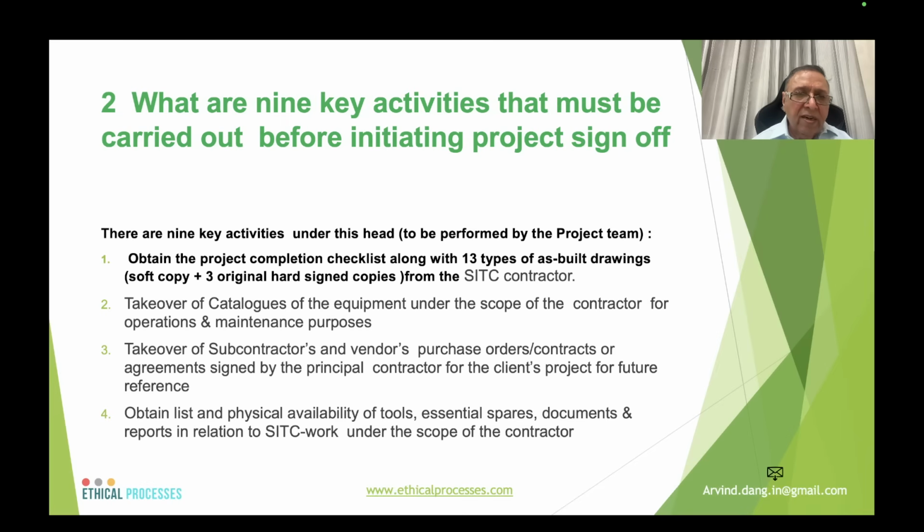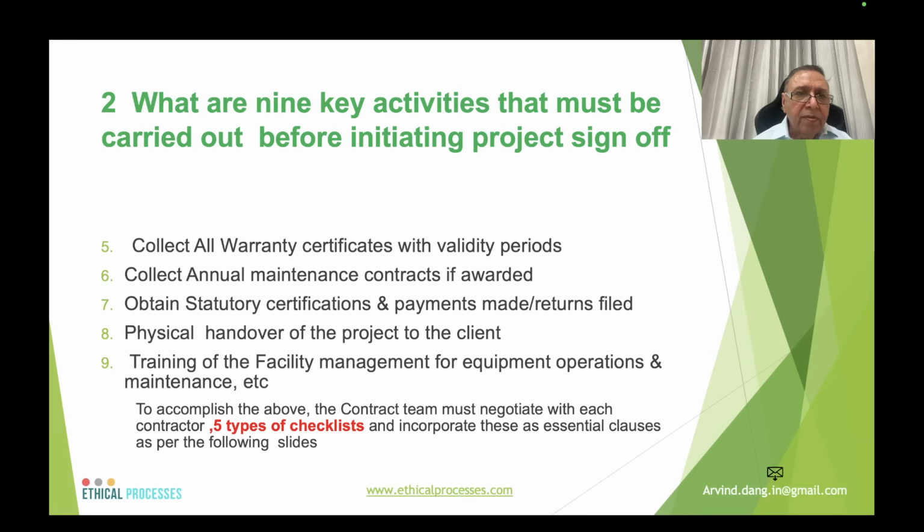4th, obtain list and physical availability of the tools, essential spares, documents, and reports in relation to the SITC work under the scope of the contractor. Collect all warranty certificates with validity periods for all the equipments etc. supplied. Collect AMC contracts if awarded. 7. Obtain statutory certification and payments made, returns filed if it is in the scope of the contractor. Physical handover of the project to the client, training of the facility management for the equipment operations and maintenance, etc. Now, facility management could be either outsourced or could be in-house.